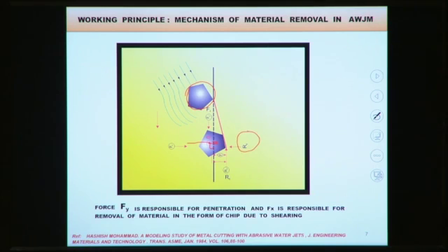So this Fy helps in penetrating the abrasive particle into the workpiece surface, which is resisted by the reaction force Ry, and there is another force, Fx. This force Fx helps in cutting from the workpiece surface. So Fx helps in the cutting operation, and Fy helps in penetrating into the workpiece surface. Fy is responsible for penetration and Fx is responsible for removal of material in the form of chips due to the shearing action from the workpiece surface.